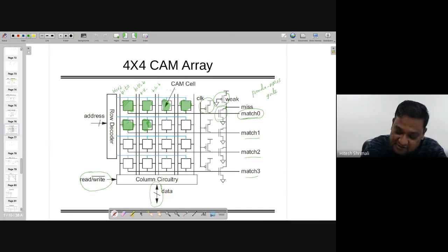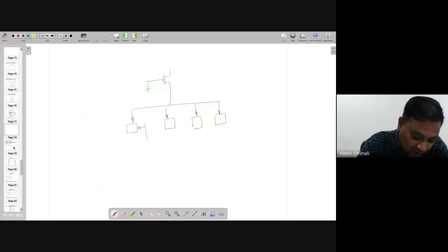So there is one transistor here, but other matches are in parallel. Such a structure makes the memory a NOR, right? Because all NMOS have the structure in parallel, you are going to have the NOR logic, right? Or the other way around, you can use NAND or whatever is given at the beginning. In this particular case, it's NOR logic with the clock, right? So this is what TCAM is about.